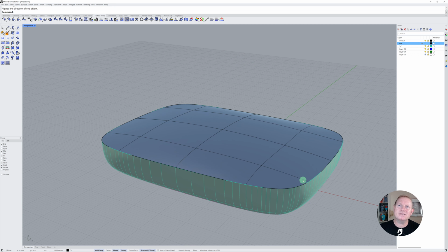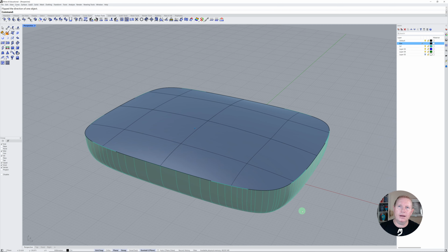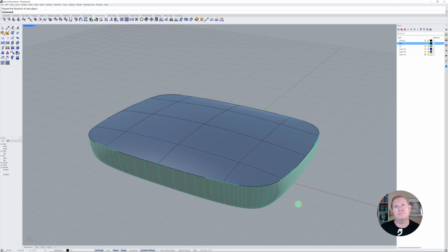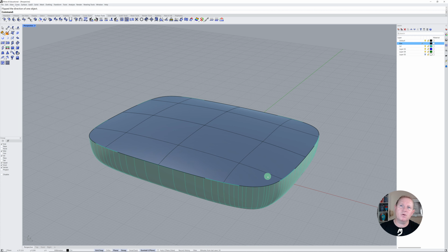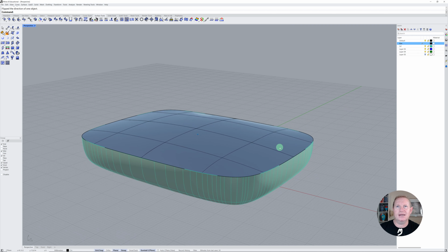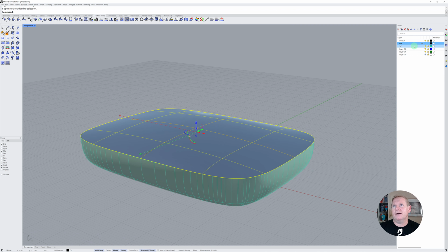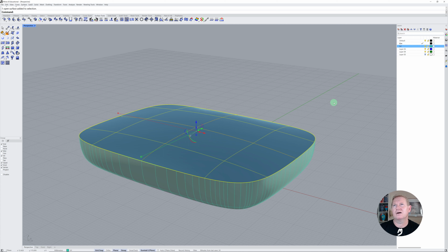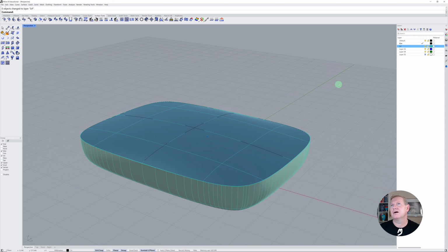Now because this surface is built to 0.001 millimeter tolerance, which is good for millimeter dimensions in small models, these 2 surfaces won't actually join together. And we'll have to do a little bit of extra blending, which we want anyway, because we're not going to fillet these. We're going to do surface blend so that we get nice curvature control over them. Just change that.